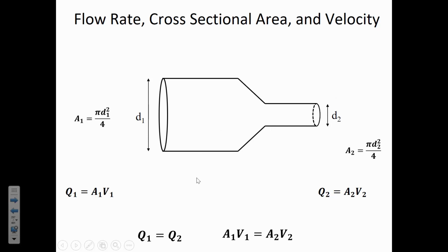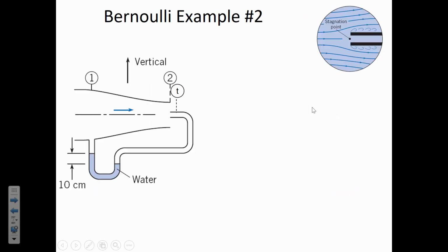So this is just the general idea that A1 V1 equals A2 V2, but specifically for diameters decreasing, that causes an increase in velocity, a decrease in pressure. There's a risk of cavitation there. All right, so let's have this be one of these nozzles that are contracting.